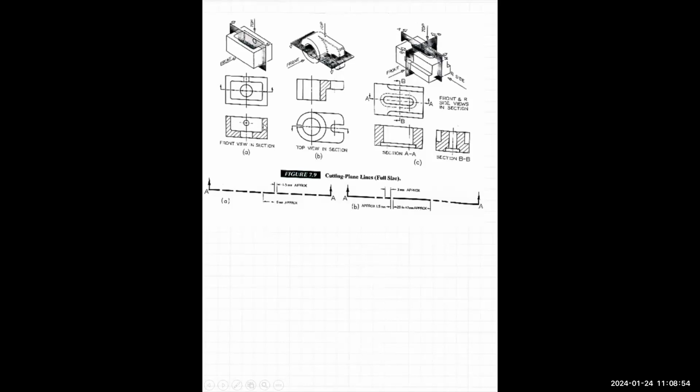The hatching goes in where the knife cuts through material. So if you think of this cutting plane as a knife, as it goes through, wherever it saw material, that's where the hatching goes. Okay? And we need the hatch to go in and we need the hatch to be visible. Not too small, or it looks like a black blob. Not too big, or it looks like 4 lines and it gets confusing, right? So a reasonable hatch scale is what you're going to want.